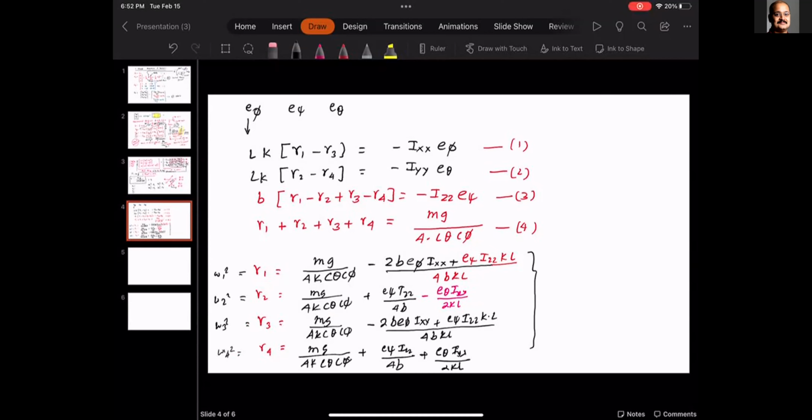Now, what happens next? The idea is, please understand, in our algorithm we need to have some value of Kp and some value of Kd. From these Kps and Kds and the errors, basically error in roll, error in pitch, error in yaw, we are going to get the values of torques.